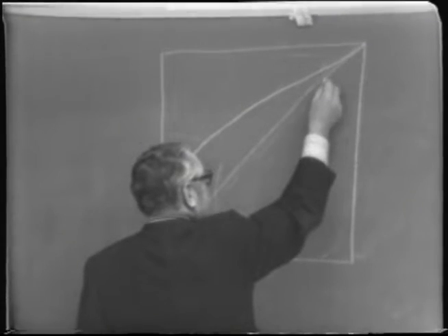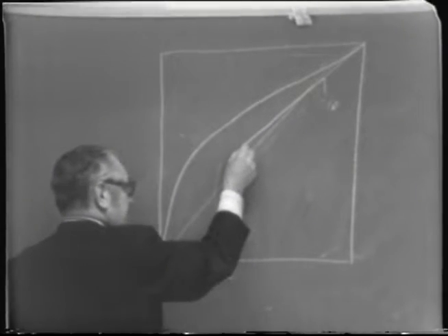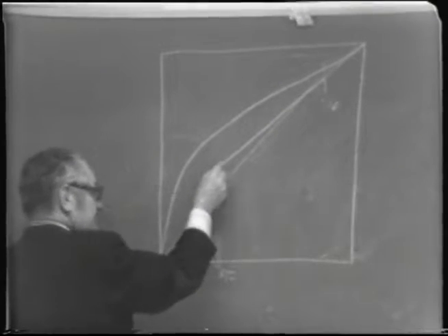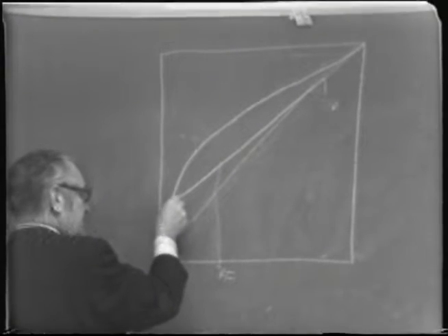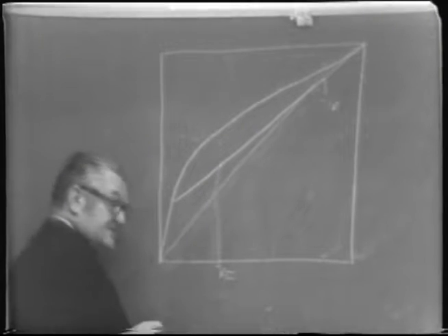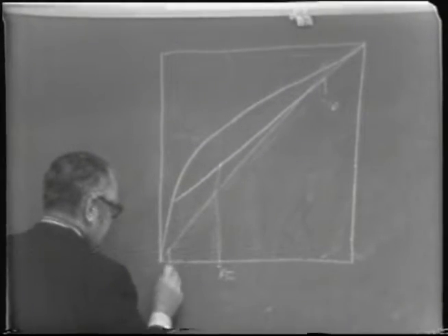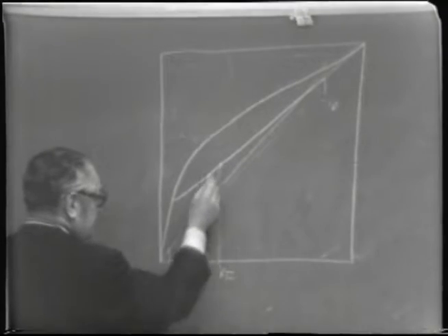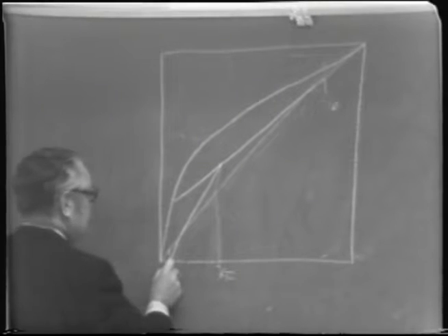So we have an operating line here determined by the reflux ratio, which has a slope something like that. Now I'm going to project this a little beyond, with a normal point of intersection with the operating line of the stripping section. Let's say if this is x sub b with open steam, we'd have an operating line for the stripping section that would come down to this point here.